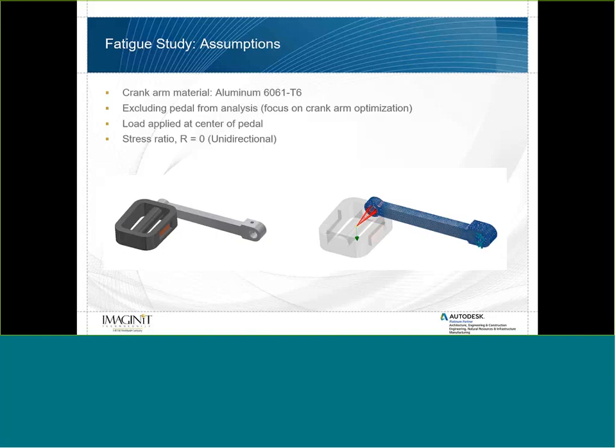Also, for my stress ratio, I'm going to be applying it in one direction and then unloading it. This is assuming that as the pedal comes around the other side, most of my load will be transferred to the other foot as I'm going up a hill. There may be some compression depending on how this is set up, but in this case I'm assuming my stress ratio is 0, and I'm applying my load in one direction and then unloading it to 0.